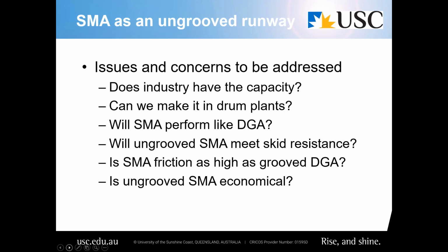Will it perform as good as dense graded in terms of rut resistance, crack resistance, resistance to moisture damage or stripping? Of course, most importantly, will ungrooved SMA meet our skid resistance requirements in the MOS? Because if it doesn't do that, then there's no point in doing any of this. In fact, even further than that, would the friction be as high as grooved dense graded asphalt friction? And in the end, is it economical? And we'll talk about the economics at the end.